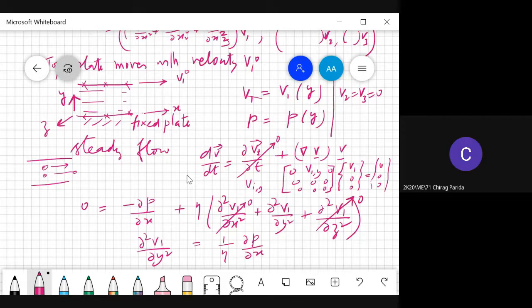Yeah, why is dv by dt zero? Just that part. Why? Sir, dv by dt is zero, like for this the acceleration is zero in the left hand side. I just showed you. Gradient of v into v. You see, all these particles are going in a straight line, and you see, velocity is not a function of x. So they will never accelerate. If you look at a particle, follow the motion of a particle. A particle will accelerate only if it had gone vertically upwards, because there is only velocity gradient. And since it is not allowed to go vertically upward, this motion is not there. Only there is horizontal motion. I told you physically why acceleration is zero of a particle.